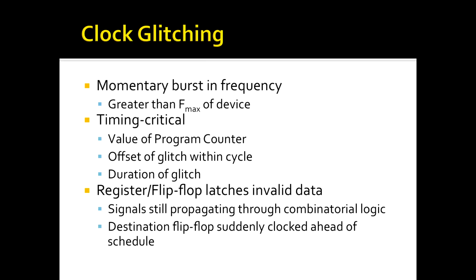So basically what this does is it causes registers or flip-flops inside the device to latch invalid data, because signals are still propagating through combinatorial logic in the device when you suddenly clock it.